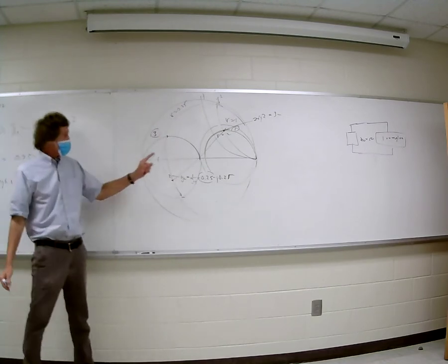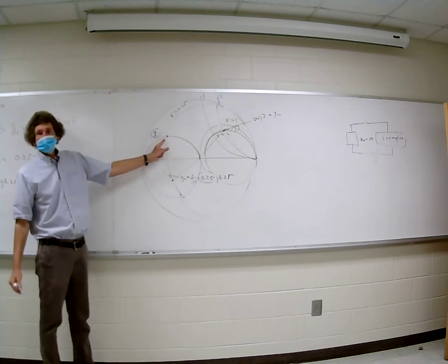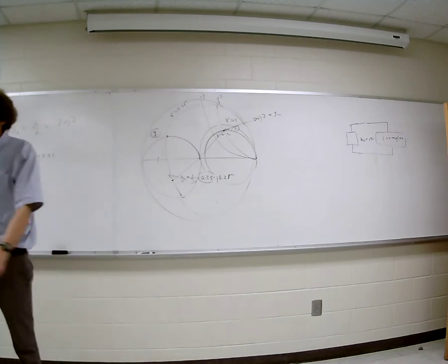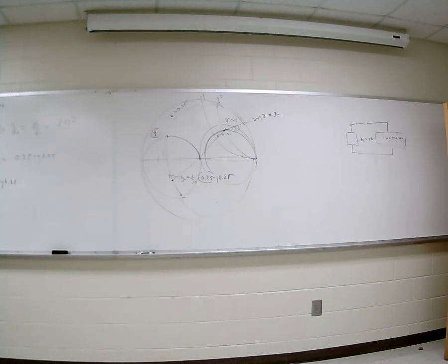So what's the value up here? Can you guys look at your Smith charts? Did you manage to draw the rotated one? You did, all right. So can you find 0.25 there? Now if you can go up, where does it hit this faint circle? Is it a straight line or curved? No. Remember, this is the circle at 1. When you add plus or minus j things, what you're doing is moving the trajectory up and down that. So if you can find out where it hits there, just give me the imaginary part.